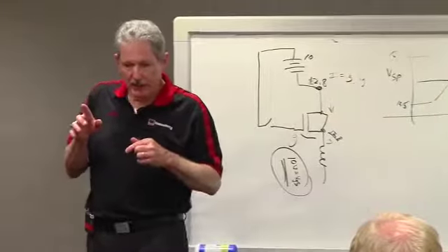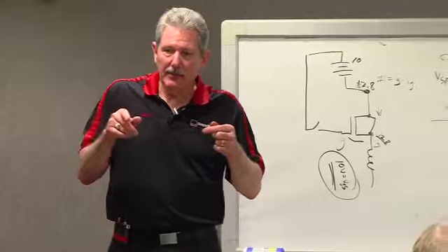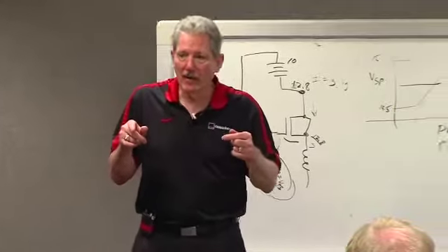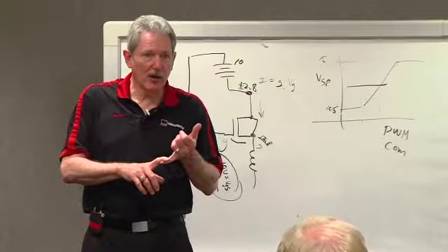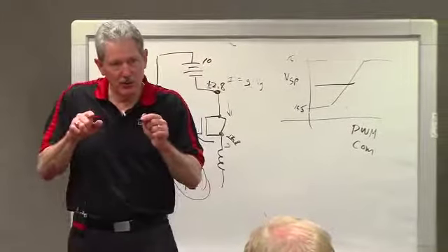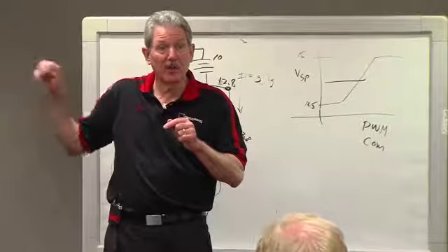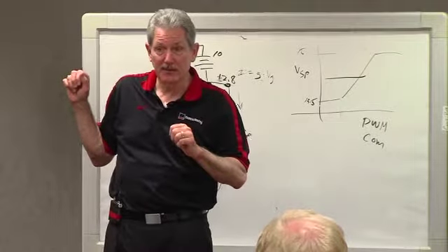Okay? Now let's look at energy management. Today, the brakes on a car work by friction. So you get wear, but also heat, and it doesn't make sense. So let's use the alternator as a dynamic brake. Remember I told you that it's 4 horsepower at 100 amps.